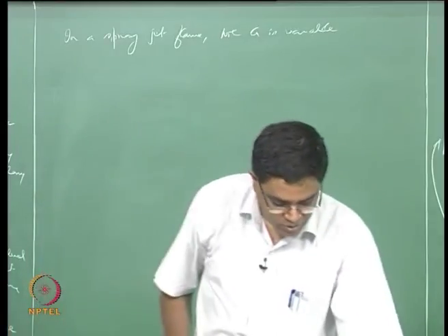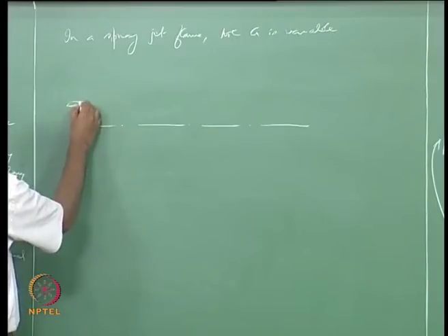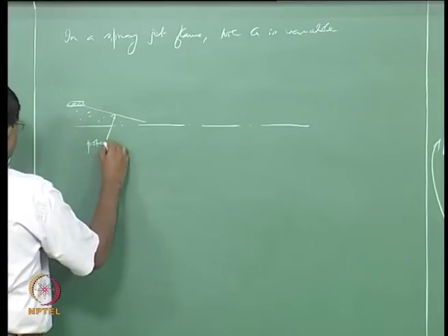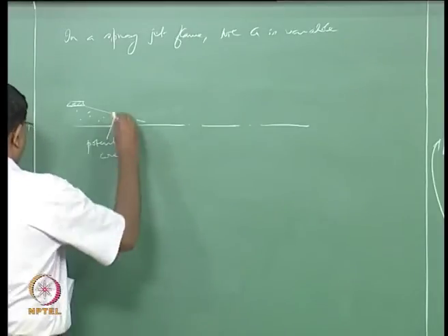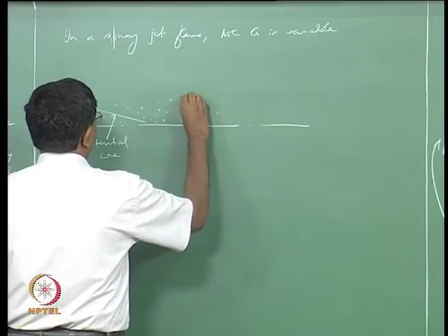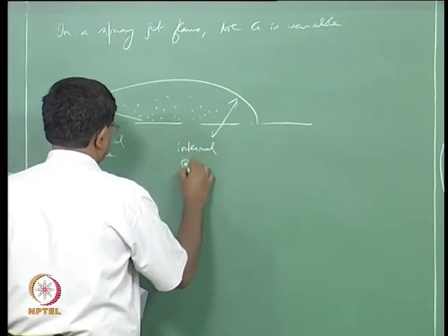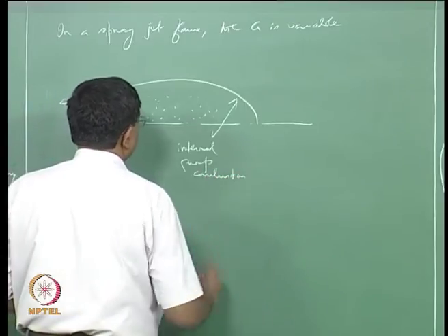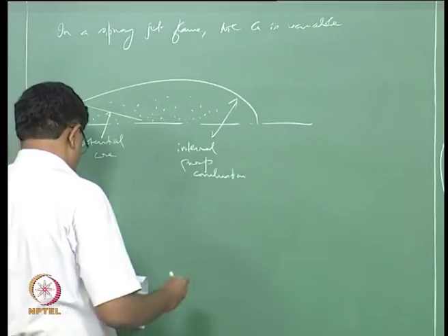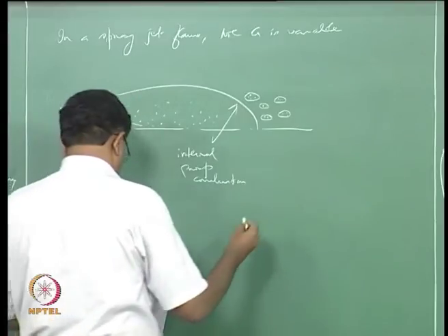So you now get into a situation where, let's suppose this is a center line, and let's say you had the lip of the nozzle which issues out this spray, and you can now think about a potential core, and near the center line you have bigger droplets, but away from the center line let's say you have smaller droplets because they are evaporating, and now you have the main flame or the internal group combustion flame, right, and outside of which as you keep going the G actually decreases and you now have lots of cloud combustion going on, right, forming the spray boundary.